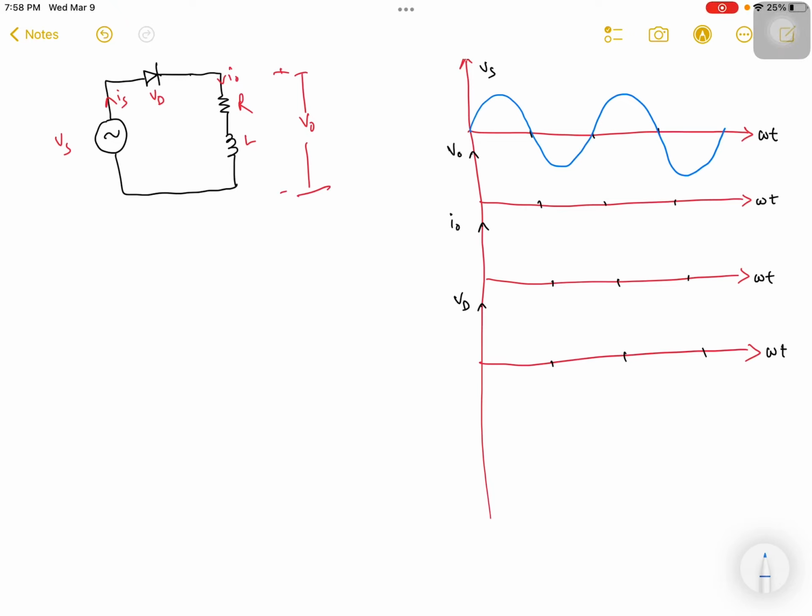This is the half wave RL uncontrolled rectifier. Now here, in place of load, we are using the resistor and the inductor, and then it is connected in series with the power diode, and the power diode is connected in series with the supply voltage. That supply voltage is AC. Your Vs will be equal to V peak times sine omega t.